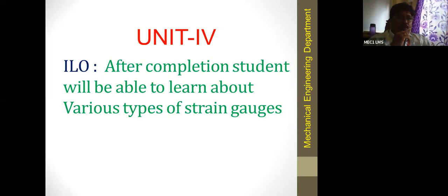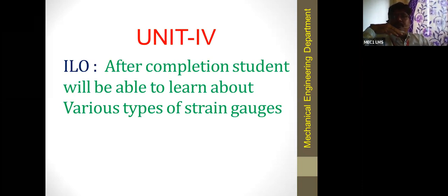From that equation, we go for differentiation by applying logarithms. And then, according to the principle of Poisson's ratio, that is lateral strain divided by linear strain. Lateral strain is a negative strain. Linear or longitudinal strain is a positive strain. We discussed that lateral strain occurs in the diameter, whereas linear strain occurs in the length.